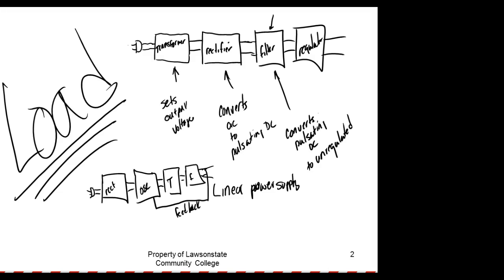The problem with switching power supplies, what did I tell you the problem with switching power supplies? They're very efficient, but they're electrically noisy. They've caused problems with the power grid, but over time they've learned how to filter. They actually filter the input. So normally right in here they'll have a pre-filter, because these guys cause weird stuff in the power grid, but they're extremely efficient, which means if this was a linear power supply, it'd probably